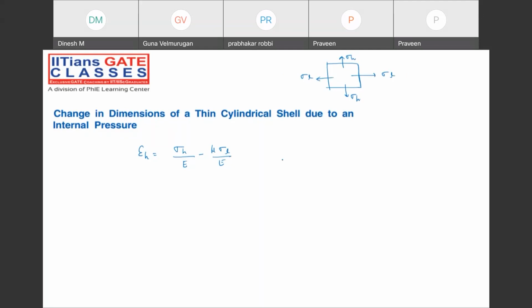So you know how to calculate the longitudinal strain. I told you the formula in the first chapter. When the material is subjected to combined loading in both directions or in all three directions, then this will be the case. Of course, in this direction we don't have any stress value, that's why it is minus something times 0. So how can you calculate the hoop strain? PD divided by 2tE. Remember, D is the internal diameter. Do not think of outside diameter, please. PD divided by 4tE.